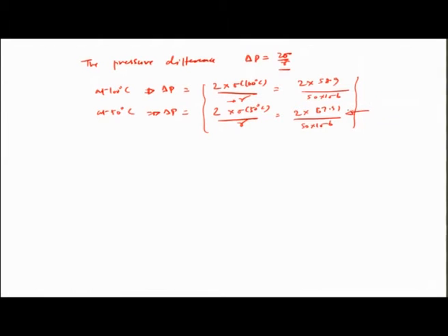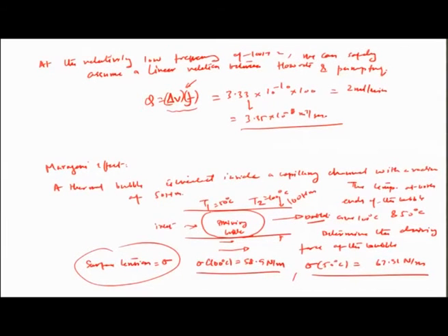Obviously, this is a higher pressure, and so it will push the bubble forward towards the low temperature. So, the total actuation force which will be there, let us say these are P1 and P2, is delta P2 minus delta P1 times the total interfacial area of the bubble A, and if in this particular case we assume the pressure to be perpendicular to the surface of the bubble. Let us say the pressure is coming and the contact angle is basically 0. So, you can assume these to be somewhat flat at both the ends.